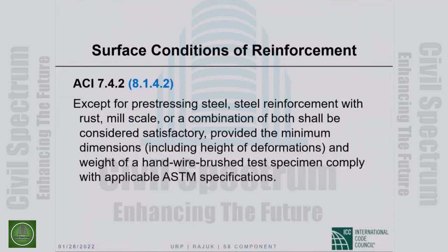Except for pre-stressing steel, steel reinforcement with rust, mill scale, or a combination of both shall be considered satisfactory. There's absolutely nothing wrong with rust. It gives us bond.